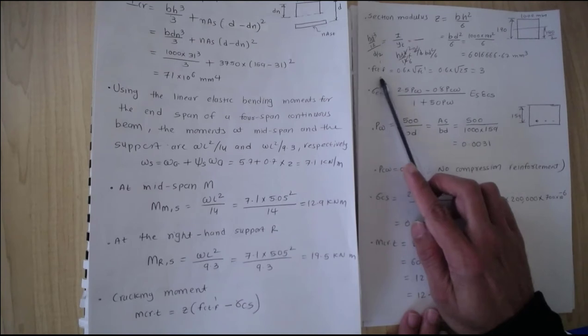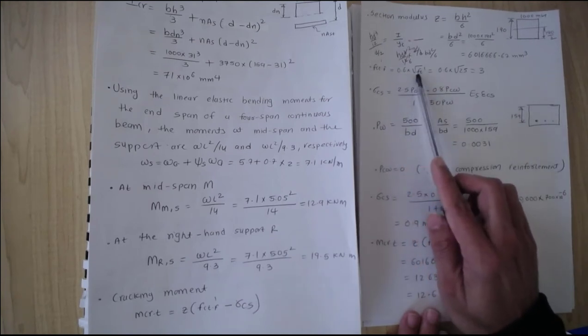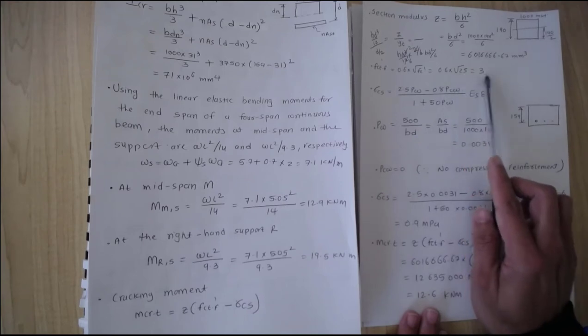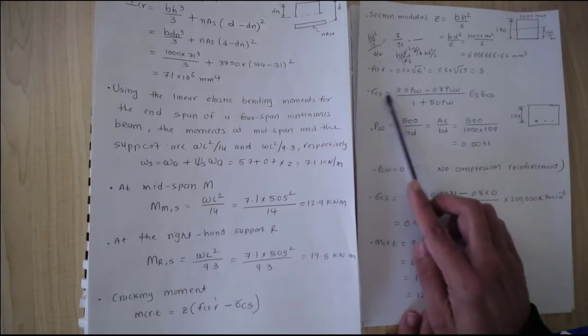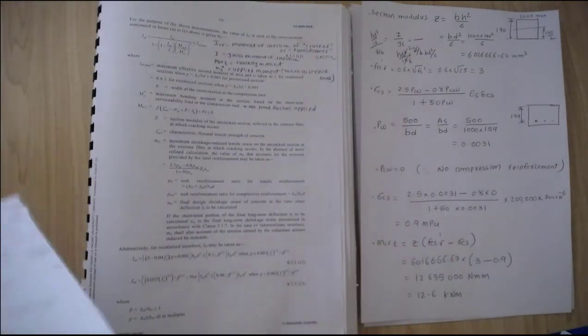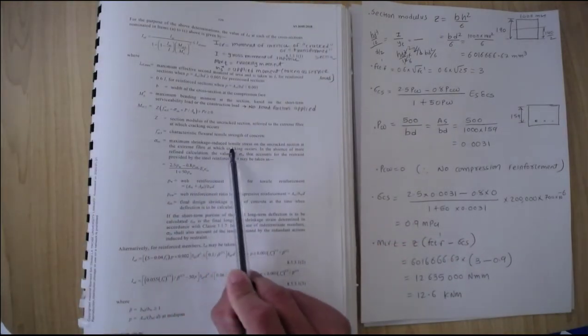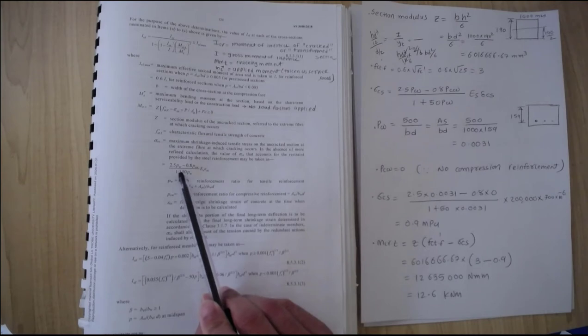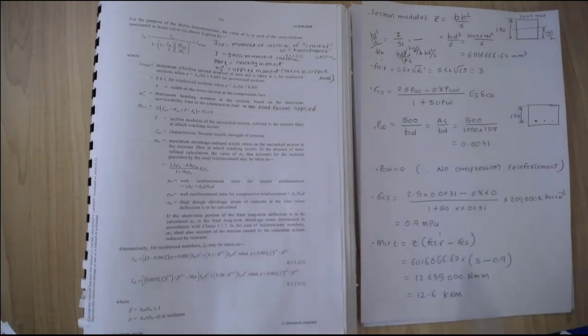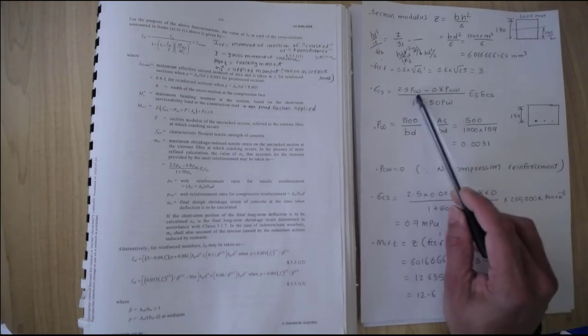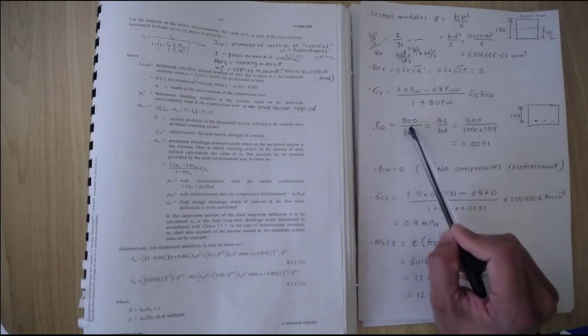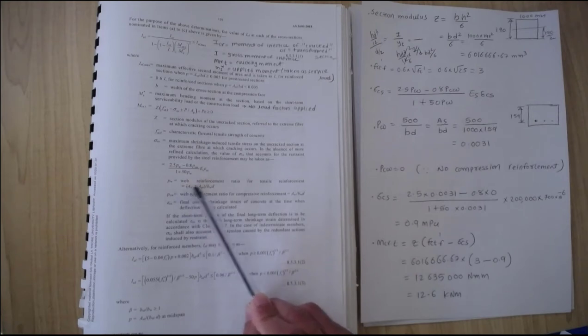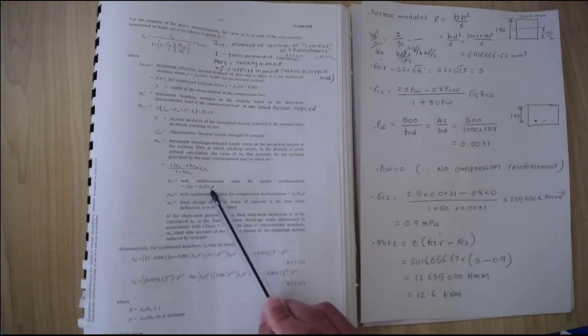Now the characteristic tensile strength of the concrete we already calculated: 0.6 times square root of f'c, 25, is 3. Sigma cs is called the shrinkage tensile stress, and it has this equation, 2.3 pw, copied here. In that one we need to look for a couple of parameters. Pw is given here, the tensile reinforcement ratio, Ast over bd.